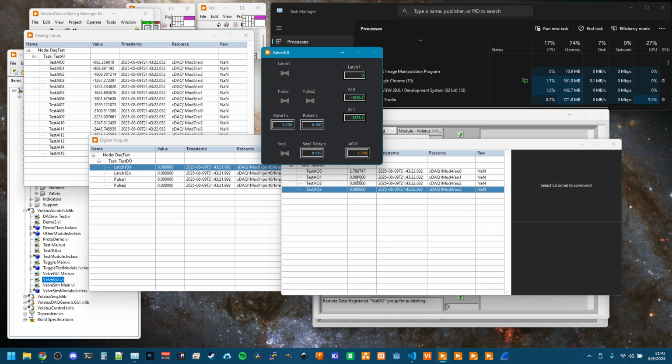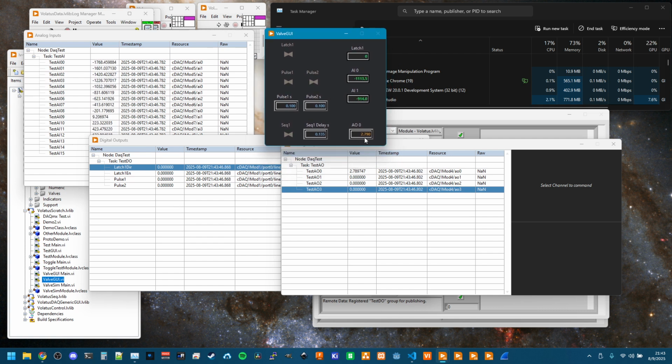There is also scaling configuration that can go in the JSON file. So if I was setting a set point for an electronic regulator, I wanted 100 psi of gaseous nitrogen out of it, of course, we could set all the scaling up so that the 4 to 20 signal or the 0 to 10 volt signal or whatever it is that goes out is scaled properly to get that end effect. But right now, everything just has no scaling configured for simplicity.